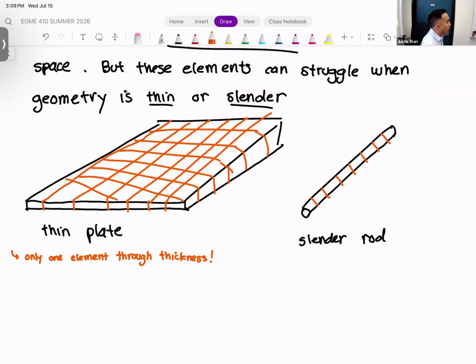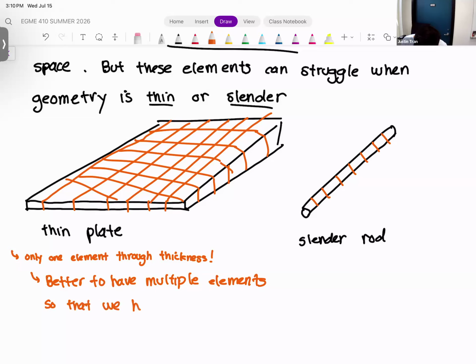I believe we talked about it in activity 2. If you're going to be producing a mesh with solid elements, you want to make sure that there are at least two, and even more, elements through the entire thickness of whatever part you're looking at.